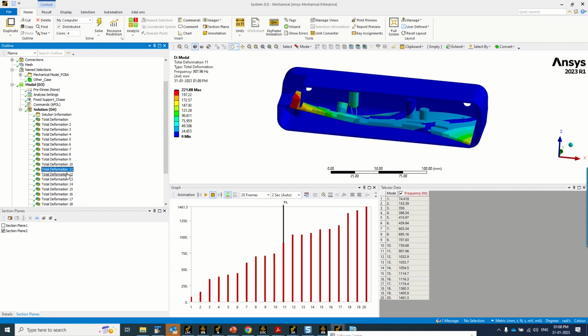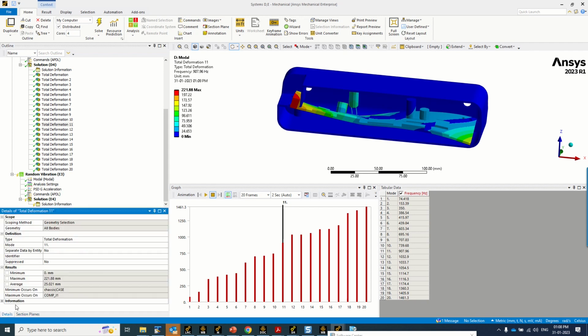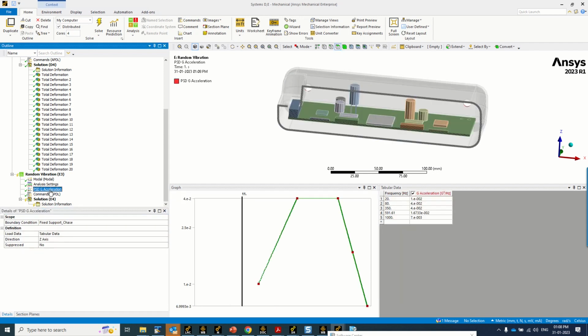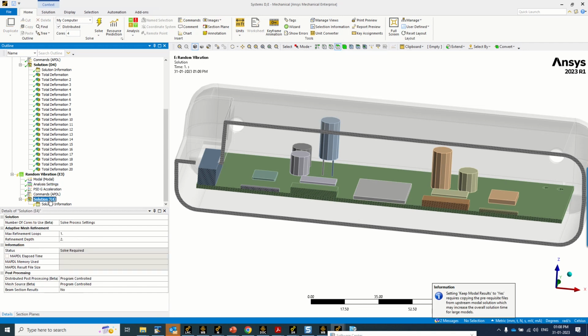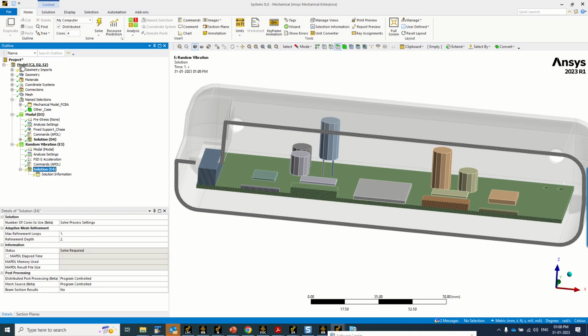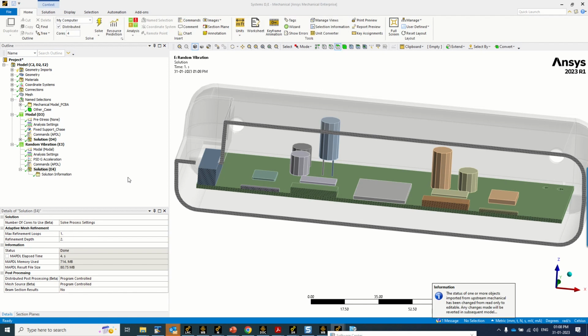Okay. All right. Now, having solved that, we see a fair amount of natural frequencies within the excitation range. So we must go for a random vibration analysis. Let us set up the random vibration analysis. We have already set it up and provided some damping, and let's solve this problem, the random vibration analysis. It should be relatively quick.